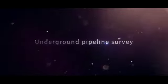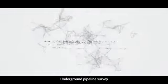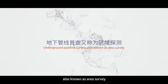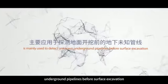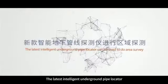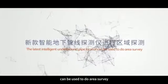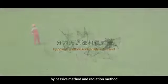Underground pipeline survey. Underground pipeline survey, also known as area survey, is mainly used to detect unknown underground pipelines before surface excavation. The latest intelligent underground pipe locator can be used to do area survey by the passive method and the radiation method.